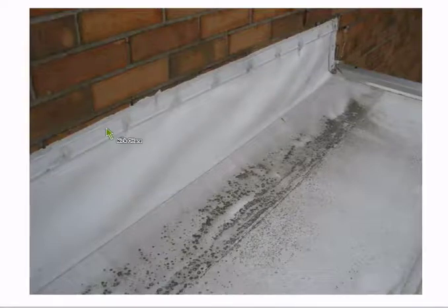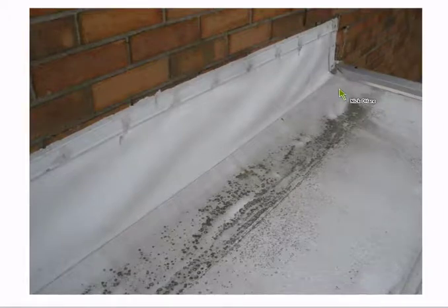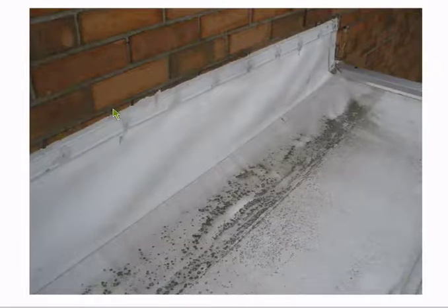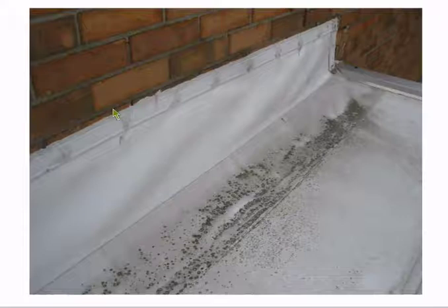Those rawl plugs might come loose. Now, really, all we're relying on is that top bead of sealant holding up. So we would expect this to leak. But typically with sealant, you're looking at what? It's minimal. It's 5 to 8 years, and if you're putting on a 10 to 20-year roof, expect a call back on that. Yeah, exactly.